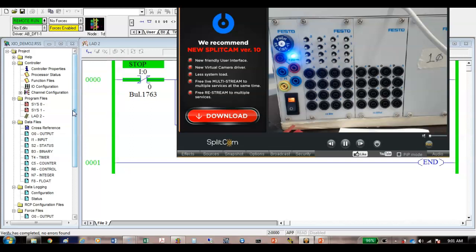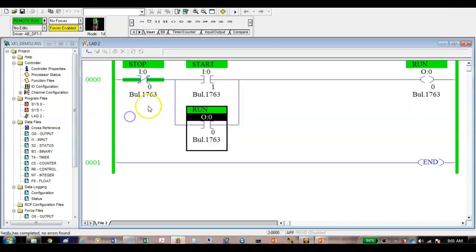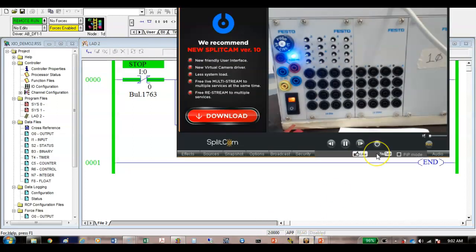So what that means is, if you take motor controls, I can see it right off. And the guy that wrote this book does the same thing. He'll draw a normally closed push button in the circuit, and then he'll come over here and use an examine if open instruction. So I'm going to go offline, and I'll wire this up. I'm going to wire it up in a minute. And that's good because y'all can see how we'd actually wire these up to the PLC. Of course, I'm not going to wire it up here. I'm going to wire it up to these output panels here.